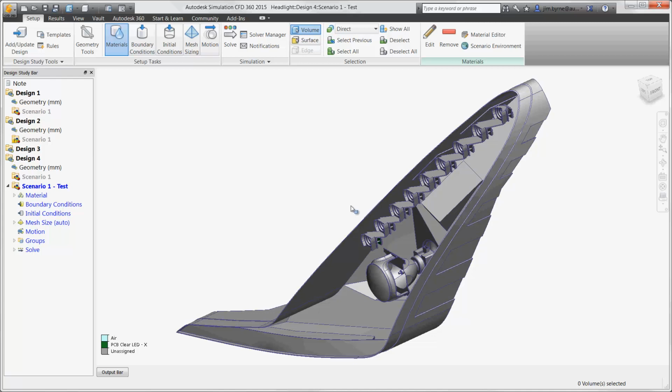As you can see, we have 4 different designs for virtual testing. We'll show the differences between them when we get to the decision center. Comparing the results between them will help us to answer key questions. Will heat sinks be needed? What are some ways to direct airflow due to buoyant forces? Should we add vents to the housing? And if so, where and how big do we make them? These questions can be accurately answered before a single physical prototype is made.